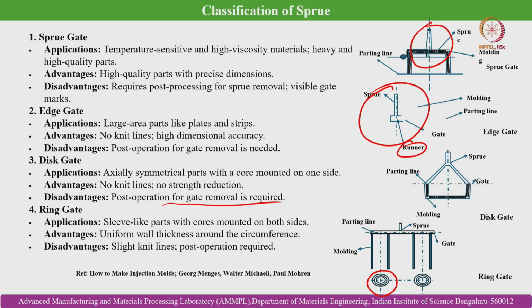If it is a multi cavity mold, this also ensures that all the component cavities receive the melt at the same point of time at a comparable speed, so that there is no difference in the morphology and properties.